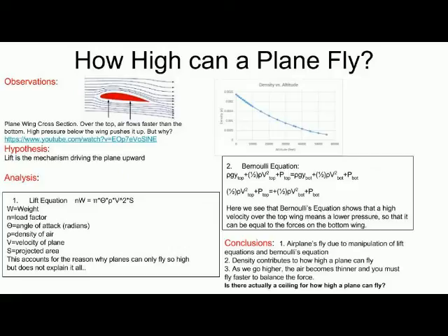The Bernoulli equation states that with an increase in velocity comes a decrease in pressure. Higher velocity of flow, lower the pressure. However, there are differences in pressure between the bottom and the top, because air flows differently over the top and the bottom. Over the top of the blade, a greater surface area would create a different type of pressure. The pressure loss over the top surface is greater than that over the bottom. This pressure difference creates a net positive force upward.